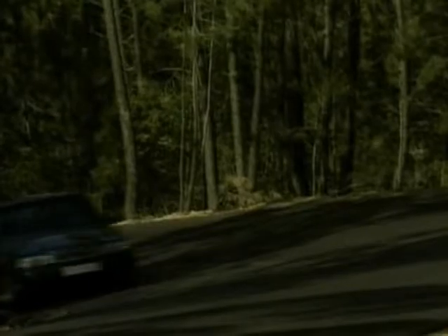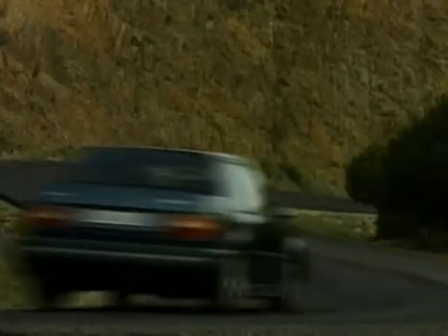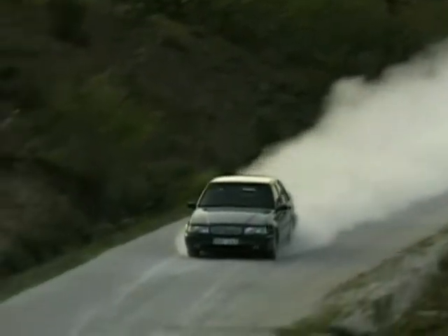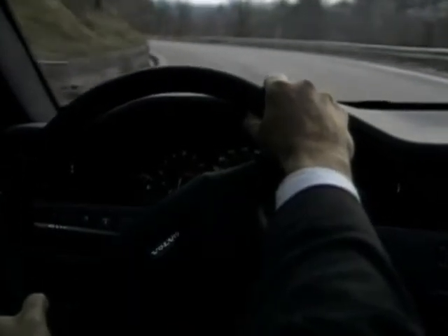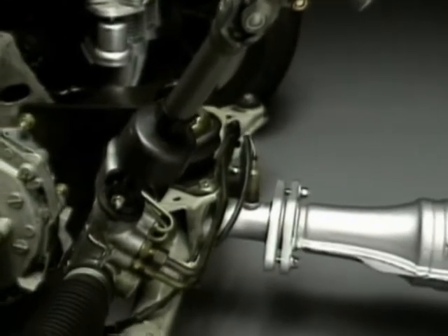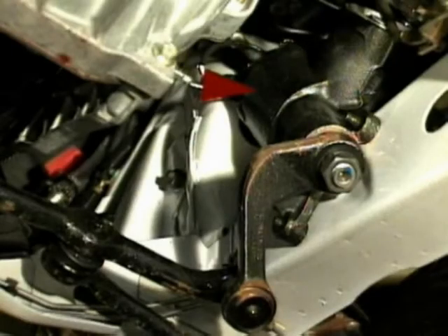This section examines principles of steering. The steering system must provide control over the direction of travel of the vehicle, good maneuverability for parking the vehicle, smooth recovery from turns as the driver releases the steering wheel, and minimum transmission of road shocks from the road surface. The effort by the driver is transferred from the steering wheel down the steering column to a steering box. The steering box converts the rotary motion of the steering wheel to the linear motion needed to steer the vehicle. It also gives the driver a mechanical advantage.